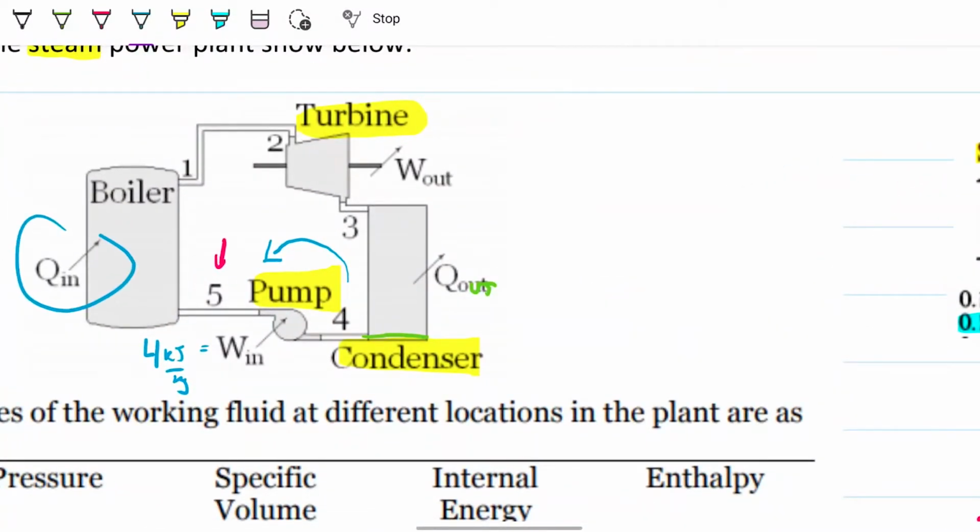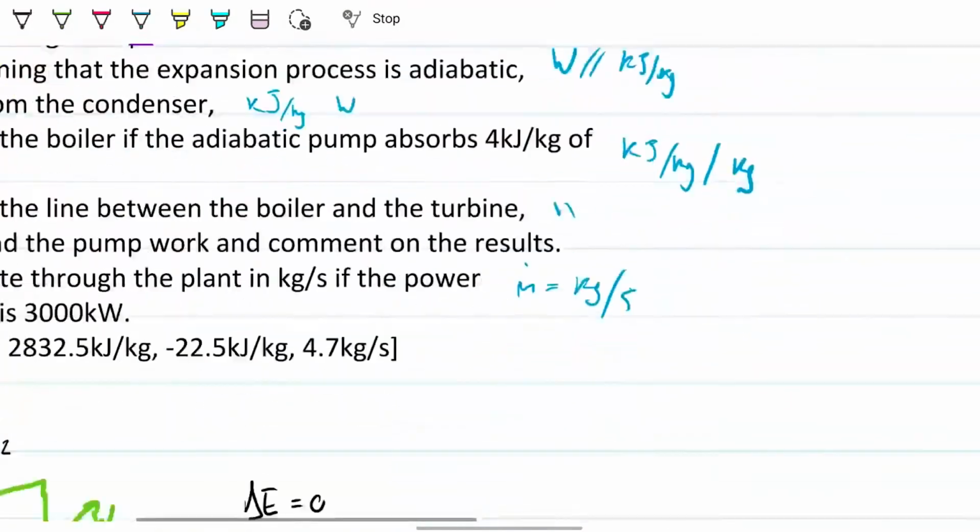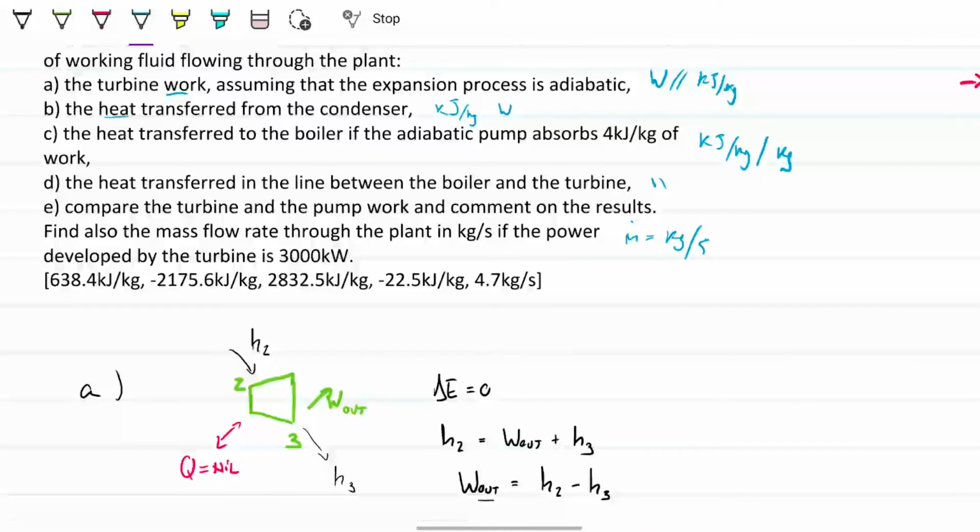We're putting some energy here. Steam power plants like to use coal, natural gas. So we put in natural gas, we burn it up, we use that energy. This is the Qn coming out from this fossil fuel. We use that energy to boil the water, so we're giving energy to the water. The water then goes to the turbine, we generate our work. It comes out part saturated vapor, part saturated liquid. Then we condense the whole thing, make it all liquid. Then we can pump it through the boiler again. That's the whole cycle.